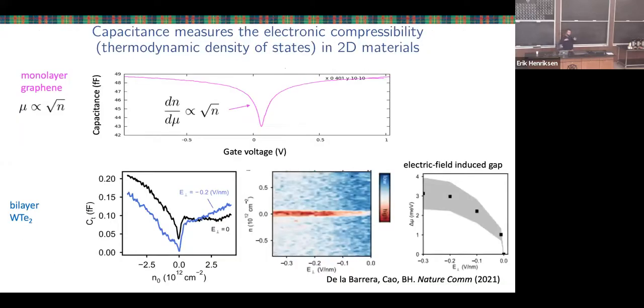All we're doing is essentially using the backgate as another parameter to change the density and the electric field. In this measurement we're just putting an AC signal in the top and measuring the change in the charge on the two layers with the HEMT. The one you were referring to would be the right measurement, but it's just much harder. It's a much easier setup this way.